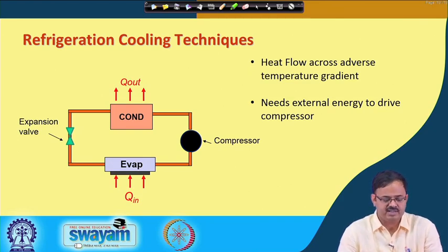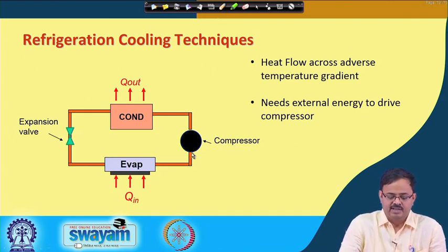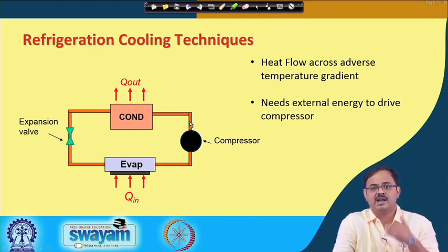Okay. So, a refrigeration system has an evaporator, which extracts heat, in case of electronic cooling from the CPU, in case of your refrigerator from the chamber inside, in case of your air conditioner from the room. Then the refrigerant comes out in the form of vapor. It vaporizes actually. The refrigerant that flows through this evaporator comes in as a liquid and comes out as vapor, and that vapor is compressed. So, what comes out of the compressor, the refrigerant vapor, is at a higher temperature and pressure,